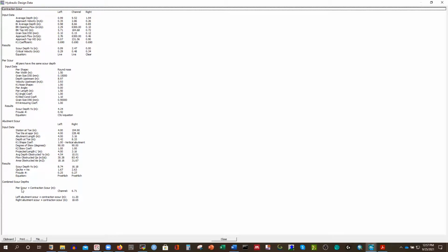So what they're summing here is pier scour plus construction scour. For the channel we are getting 6.71. So for construction scour we have 2.47, and for pier 4.24. If you sum them up, you will get 6.71. So that is for the channel, right? So you don't need to treat your bridge for the abutment while you are treating your piers, because piers are usually located on the main channel, and the abutments are on the other side.